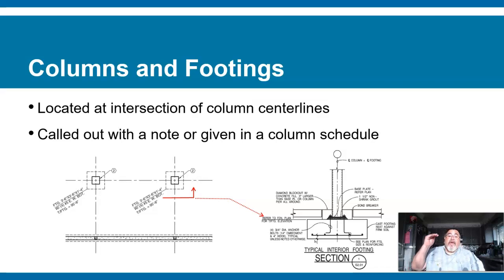They're talking about the elevation, where the top is going to be, and that number is based on the measurement above sea level. In reality, it might be 6 inches above your ground, 8 inches above your ground. Maybe your house is on the side of a hill, so you keep track of the different numbers above sea level so that you have the relationship of one floor to the other.